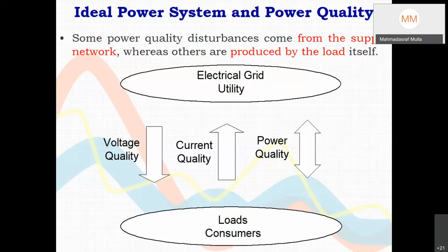We use the popular term PCC, point of common coupling. One transformer is supplying several loads. At the point of common coupling where different loads are connected, if one of the units has a major non-linear current, then the PCC voltage is nothing but the sine voltage minus the source impedance drop.